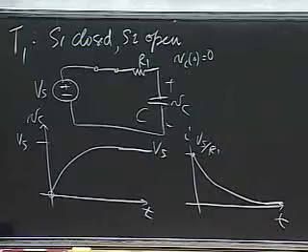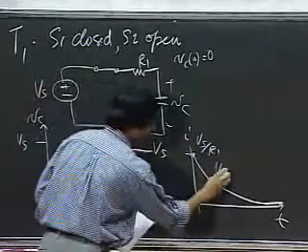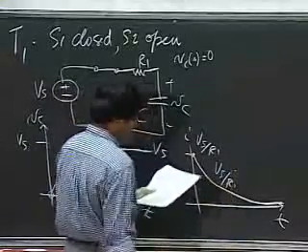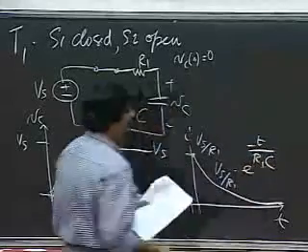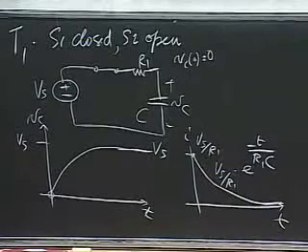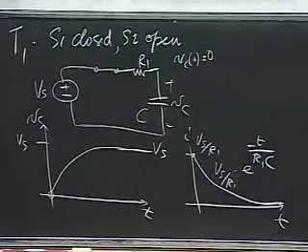I can very quickly write down the expression for the current, and that is simply the initial value, Vs divided by R1, times the exponential decay e to the minus t divided by the time constant for the circuit, R1C. Okay, so you've seen this stuff before. Here comes the part that we care about for now.